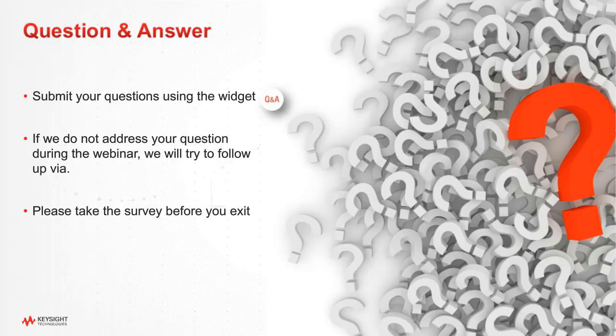It's a great question because prior to having these retimers, we tested a host or device as a black box. In other words, we didn't care what it had in there. But for USB 4, it's very specific. We have to ask, does the product have a retimer? If the product has a retimer, then we have to add additional tests. So we do the existing tests, for example, the usual JTOL tests and the I-height, I-width, etc.